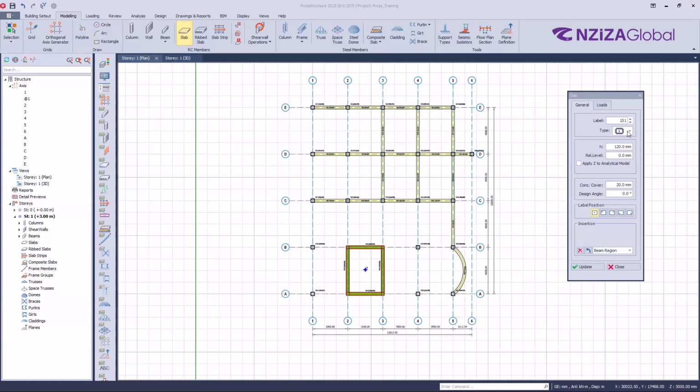So I was explaining this type of slab. We have different types of slab depending on the continuity of the slab. For instance, if we take an example for type 1, you will select type 1 when you are going to model a slab which is continuous on all 4 edges. You will see the hatched side. This hatched side means that that side is continuous.